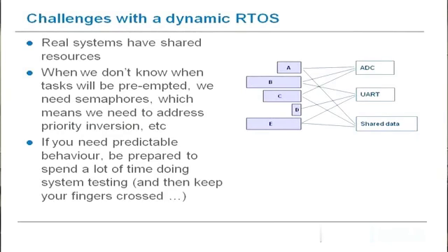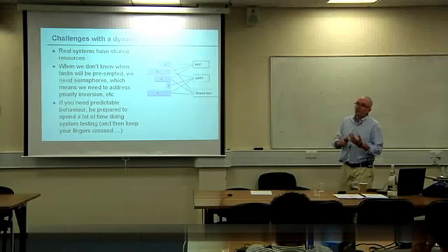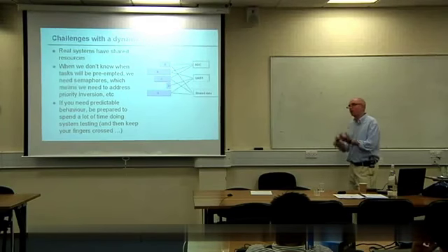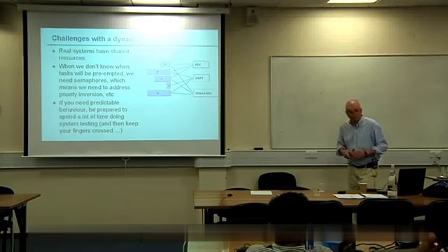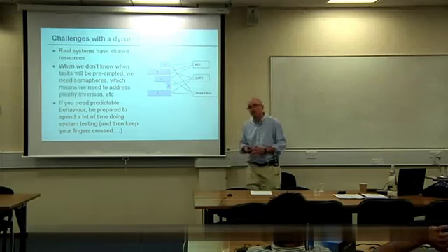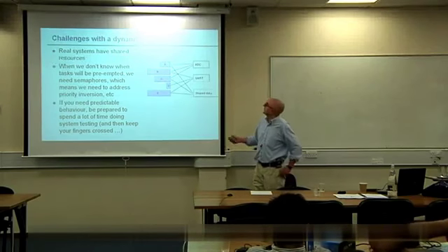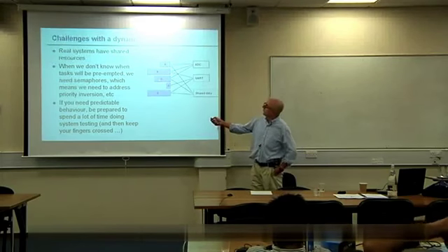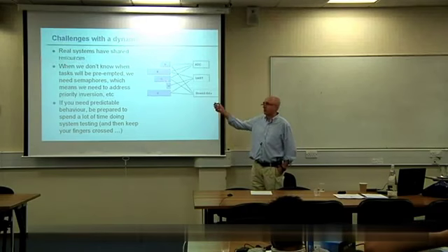The challenge we've been looking at here is we've said, okay, maybe C is using our analog to digital converter. And then B comes along, it has a higher priority, and it's blocked. So that's the origin of the problems we have. Suppose it's time triggered, this system, and rerun that scenario again. Here, C doesn't just grab that resource.